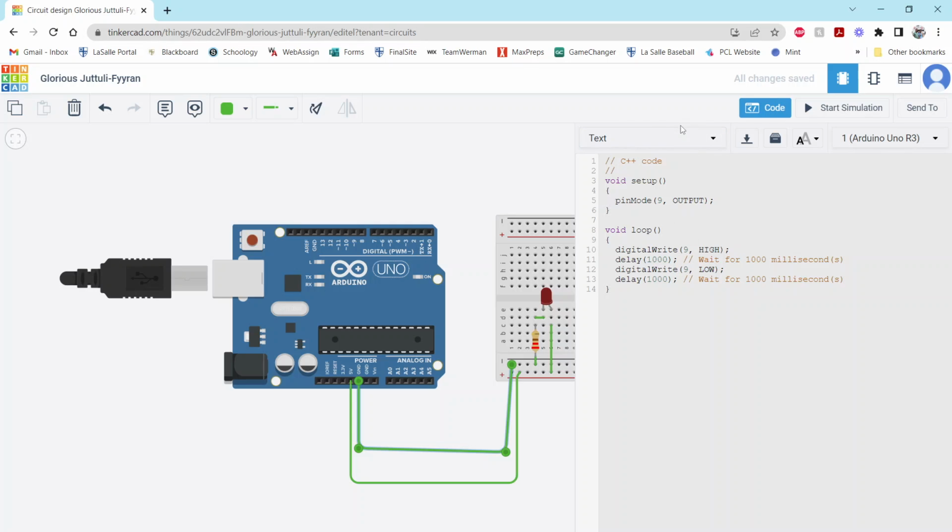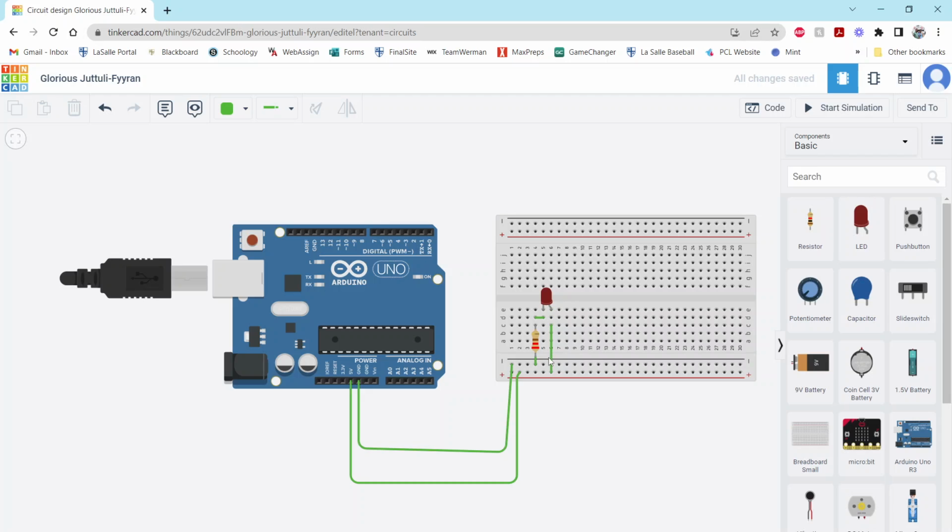So now I have some basic code here, and I'm going to go back into here, and rather than powering it from this point, I'm going to see if I can just delete this out. Should be able to delete this cable here. Oops. All right, and I'm going to run power from pin 9. And I'm going to power it up here. So yeah, we have power from here, but we're actually going to use pin 9 as an output to light my LED. So when this thing gets turned on, this power here is actually not going to it.